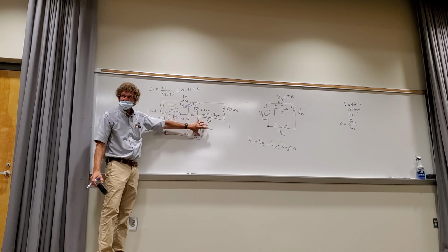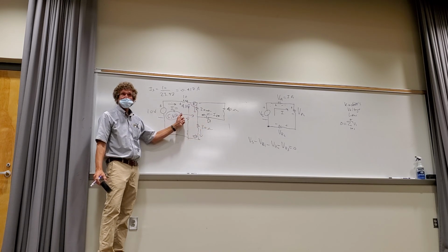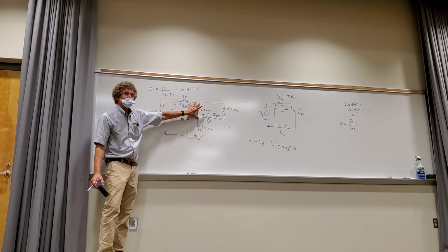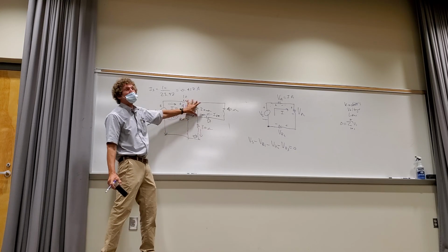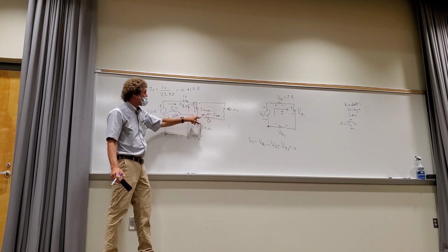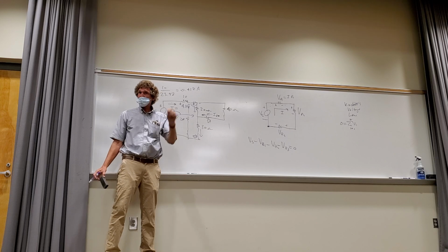Subtract whatever the voltage is there from that, and then what do you find out? That's the voltage that remains here, right? Yes, sir. Then if I wanted the current through there, I'd simply take whatever that remaining voltage is and divide it by 90, and I'd have the current. How many see that?